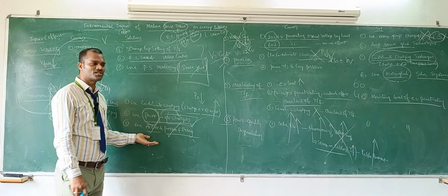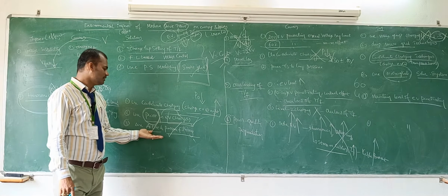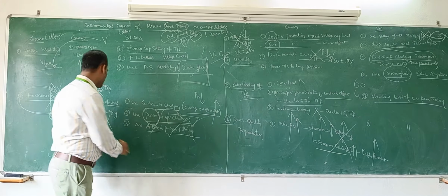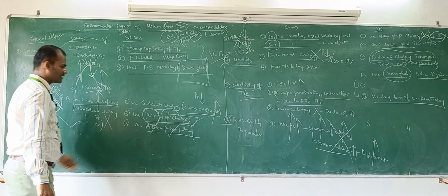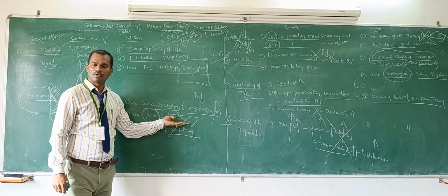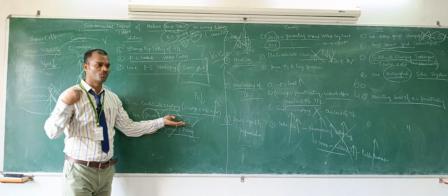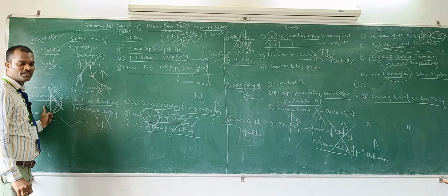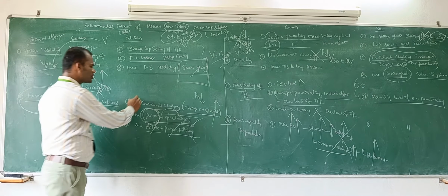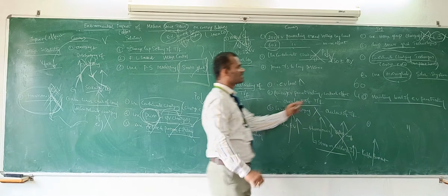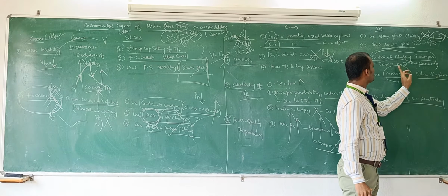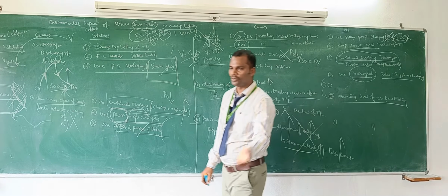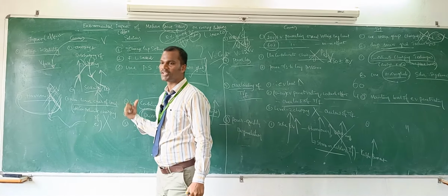Next, it can be solved. What are the possible ways we can solve from the power GENCO side? We have to use active and passive filters to eliminate the harmonics generated by electric vehicles. Use pulse width modulation chargers, which are a little bit more costly. If you use pulse width modulation chargers, harmonics may not be developed by EV chargers. And use coordinate charging, already discussed. What is coordinate charging? Charge EV only at off peak hours, in such a way that it will not create any voltage sag issues or harmonics at morning time.